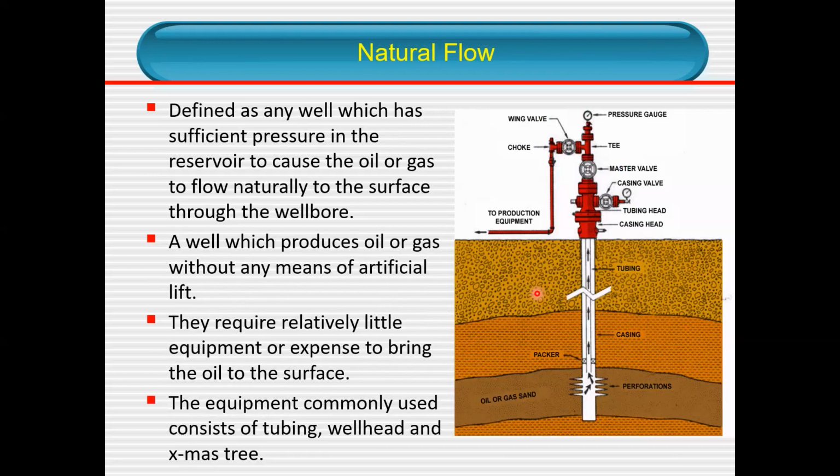All these elements will definitely come into the picture whenever the situation changes, the condition changes, the temperature, the pressure changes. This is where you start to deposit all these solids. That is why solid deposition and production cannot be separated. You will face it, and as a production technologist or production chemist, you have to face these solids issues.